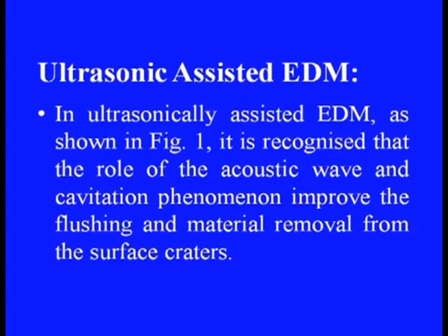This is another hybrid process of EDM. In this process, as we can see in the figure later, it is recognized that the role of acoustic wave and the cavitation phenomenon improve the flushing and material removal from the surface craters. These process conditions are significant for micro drilling and production of slots and grooves.